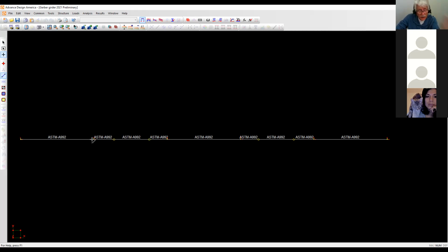And then be consistent. So this way, when you look at the results, you realize where it starts on the member and where it ends in the member. So if I go from, this is I, this is J, this is I, this is J, always be consistent. I don't care, but don't go one member there to there, and then one member there to there, and then you don't remember which one is I, which one is J.